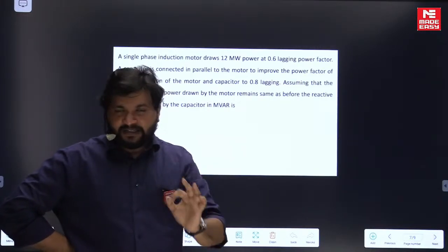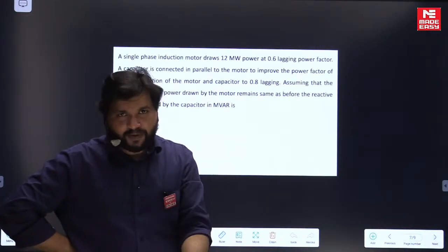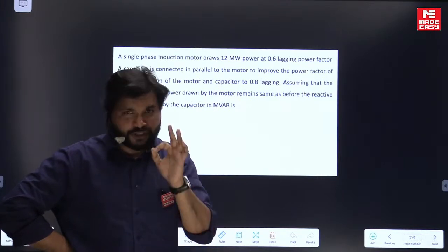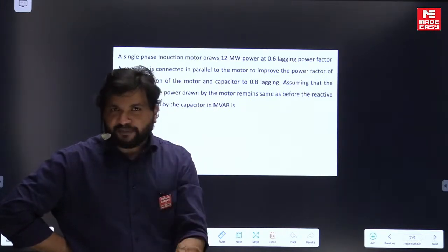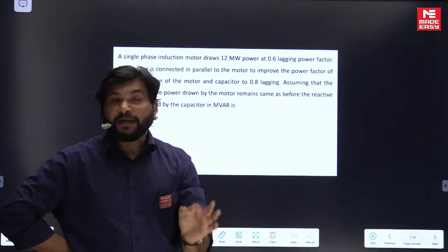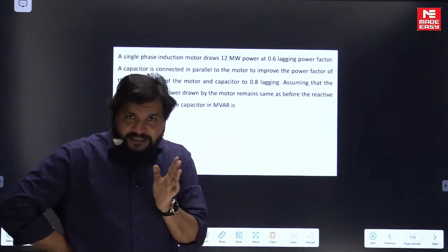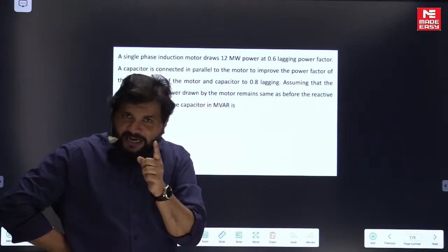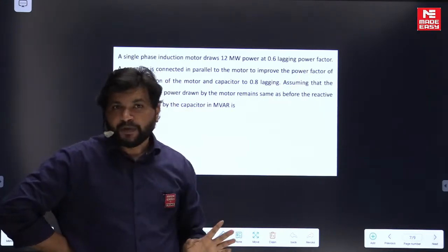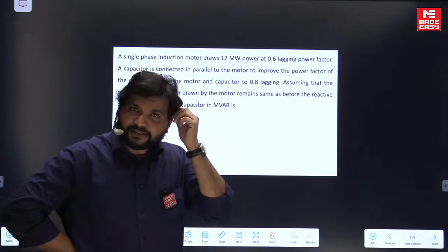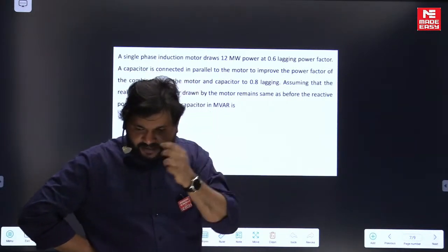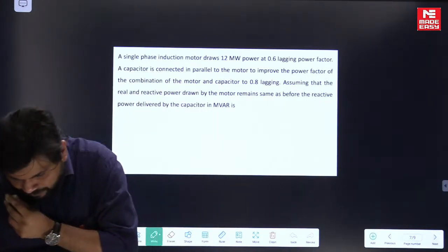It doesn't mean that the induction motor is not asking reactive power. They will ask reactive power for their operation to produce RMF. Here, suddenly the power factor is improving, which means the capacitor is going to provide the reactive power required actually. How much it is providing depends. So according to the question it is given, the power factor is improved.